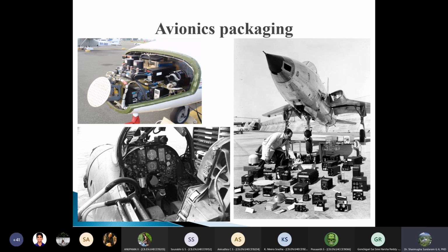Okay. So one of the standards for these modules, or the so-called packaging level implementation of the electronics, is the line replaceable unit. So the LRUs are logical and functional boundaries which are associated with the tasks that they are destined to perform within the larger avionics system and within the aircraft also. Okay. So there are two broad divisions of this concept of the line replaceable units. One of them is called the air transport radio, ATR.